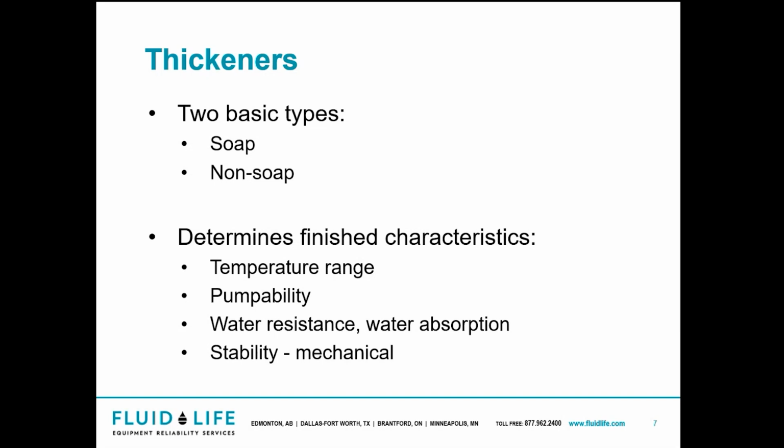So for those of you who've been in a course like this before, and are living in Houston, Texas, versus those who work at the B2 Gold site, for example, in the Nunavut territory, you're going to need very different grease applications, and different thickeners are going to be required. Pumpability: how easy is it to pump the grease? It's a lot different pumping it out of a manual lubricator, like a Lincoln knuckle breaker, or just a squeeze trigger on your grease gun, versus a centralized loop system that's running thousands of feet in length.